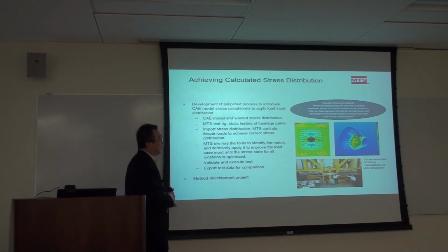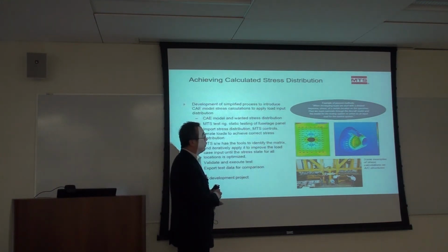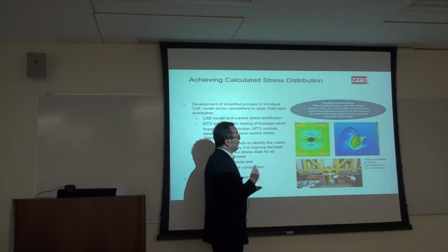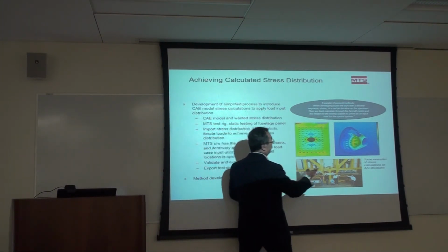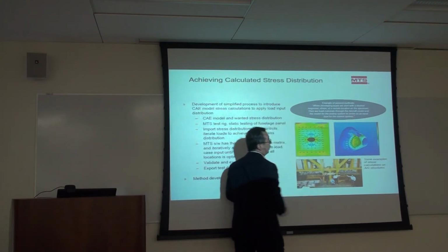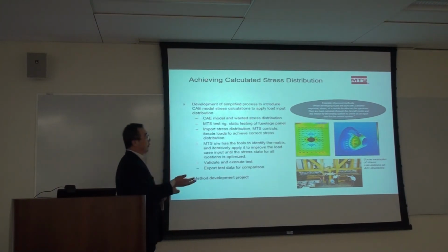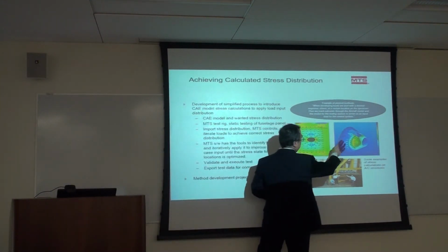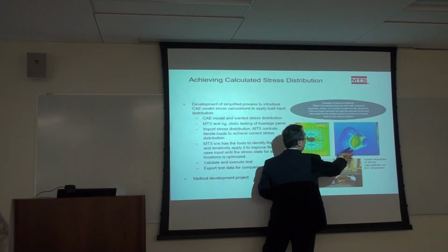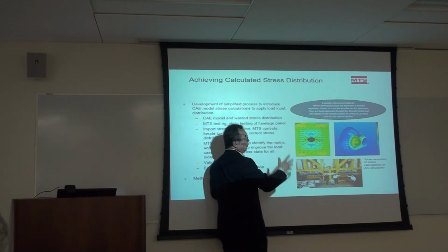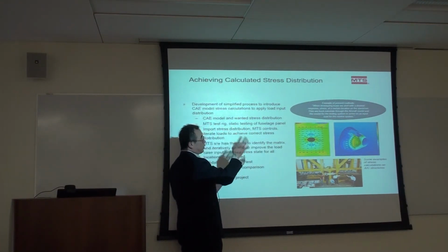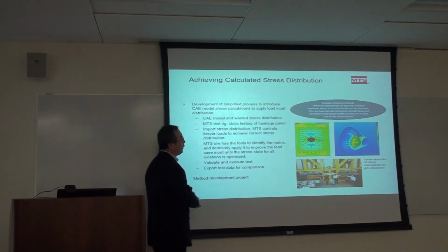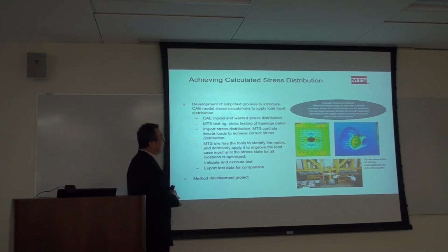For example, in some applications, FEA people set up their complicated models and solve them, and find out the strains in different locations. Then they tell the lab people, this is the strain field we calculated, and it has 50 locations. The strains we want you in the lab to reproduce using actuators.